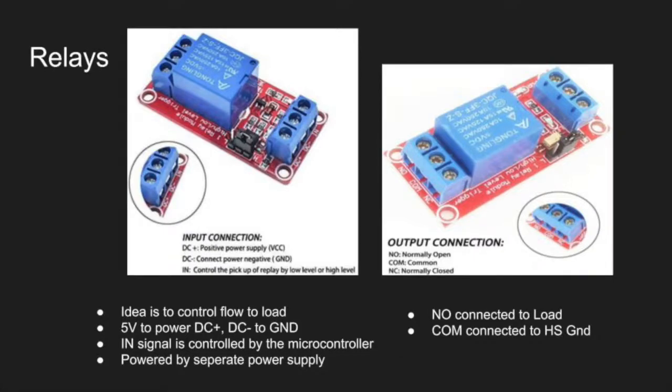There are 4 relays total controlling all 4 loads, and the TIVA controls the relays with a 3.3 volt signal. We have it set to normally open with an external DC power supply of 5 volts at 2 amps. And based on the voltages that are read in by the current transformer, the TIVA will tell the relays to turn on and off, turning the loads on and off.